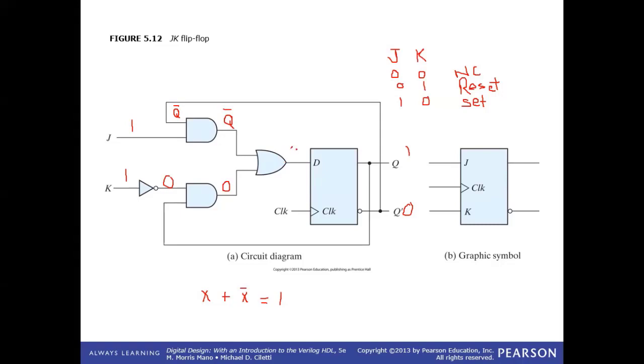It would also be that of Q bar. Yes. Can now anybody tell me that if D is being fed with Q bar, what would happen to the output of this circuit? The output will change, sir. If Q is 0 it becomes 1, and if it is 1 it becomes 0.